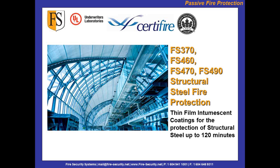So a low section factor equates to a stocky section, which when unprotected will take longer to heat to a set critical temperature than a relatively slender section, which is a high section factor. The inherent fire resistance of a stocky or big section therefore requires it to have less fire protection to achieve the same fire resistance rating.